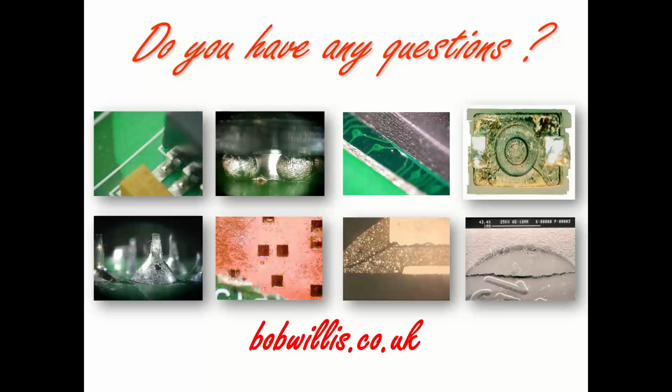Originally, a lot of components which were high temperature, which were designed for wave, but the actual connector body came into contact with the solder wave when we were doing tin lead technology at 250, 260 degrees C. You could see the differences in some suppliers' parts. You could always see small little cracks with the part that made contact. Even if you wrapped it in Kapton tape, which a lot of people would do in those days, you could see these little cracks. But some suppliers, different type of plastic, no problem at all.